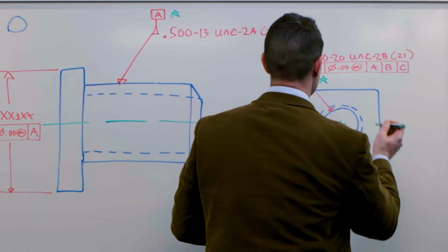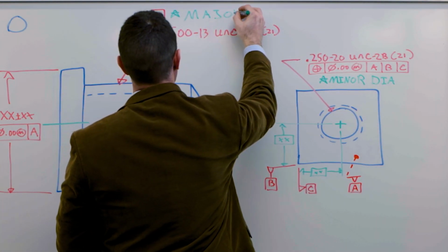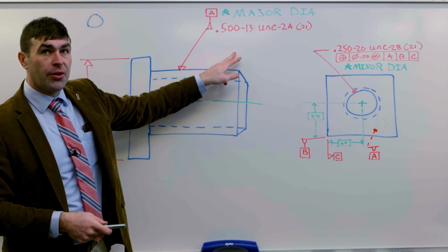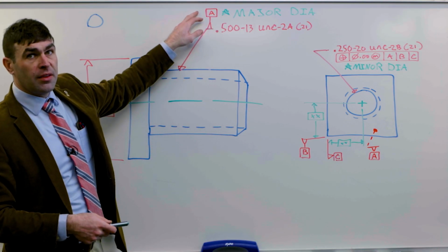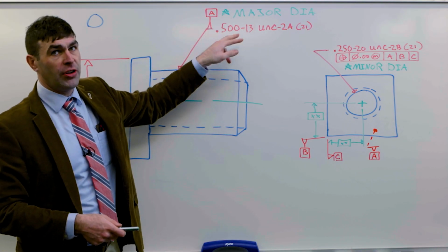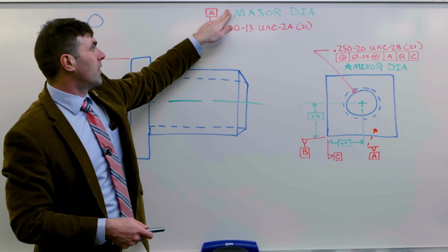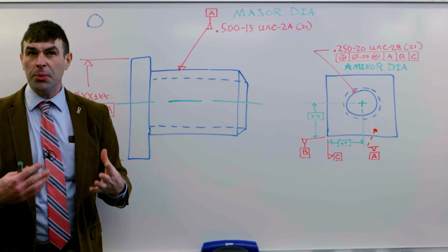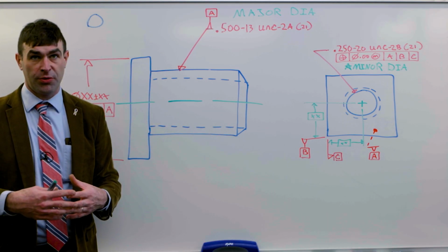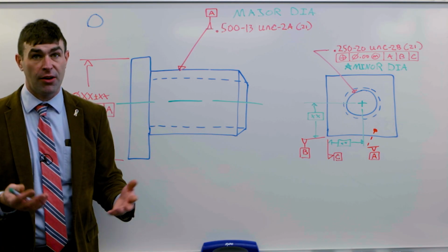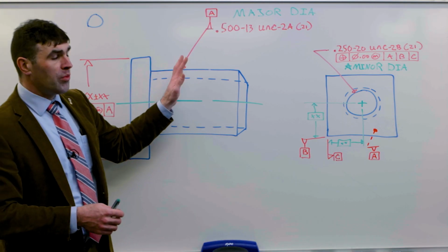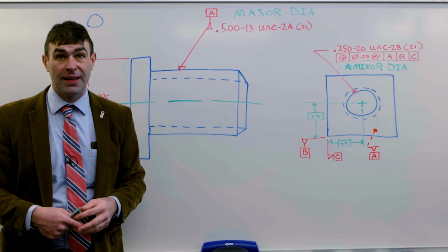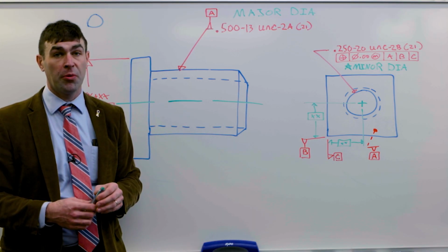So, just like I quoted a minute ago, for an external feature, adjacent or beneath the datum feature symbol, and I've chosen adjacent here, we'll just write major diameter. Now, normally I like to spell things out, so just write diameter. Letters are free on PDFs, basically. Y14.5 specifically indicates this as an example. So either way, in my opinion, is correct. Maybe this saves a little bit of room on the drawing.